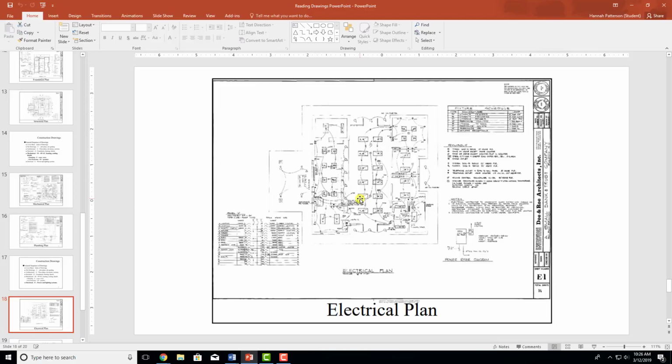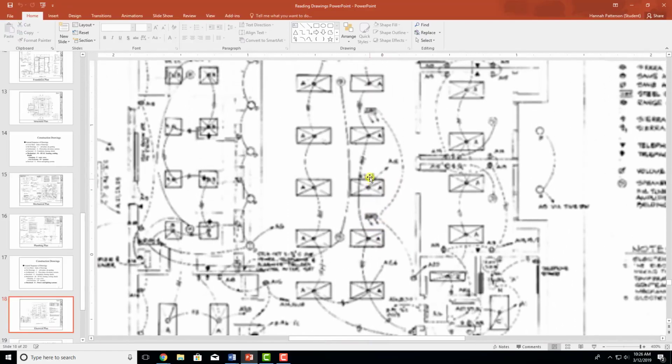And we'll get into this a little bit also on the Planet Mazda ones, but these are all the lights, and then the lines between them show the connections. So all of these different ones, that's a light, a light, a light, a light. These are all lights, and if you look closely, I don't know how good the resolution is, it has an X through it, which indicates a light. If you're looking at a reflected ceiling plan, you might see ACT squares, your acoustical ceiling tiles, and they'll look just like this, except they won't have an X. So that X means it's a light.